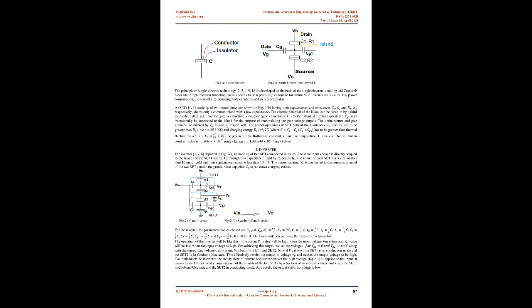In classical electrodynamics, current can't flow through the insulating barrier. But in quantum mechanics, there is a positive probability, i.e., more than zero, for an electron residing on one side of the barrier to reach the other side when the proper bias or input voltages are supplied. If bias voltage is applied properly, there will be a current flow. Neglecting other effects, in accordance with first order approximation, the tunneling current will flow in proportion to the applied bias voltage. In electrical terms, the tunnel junction shown in Fig. 1a behaves as a resistor having a constant value depending on its barrier thickness.